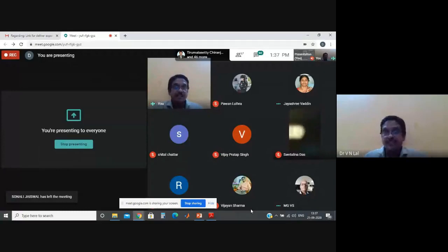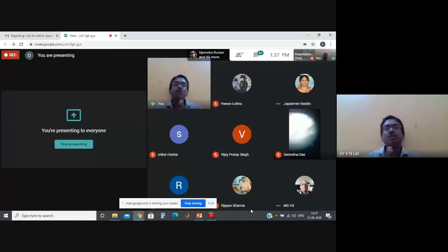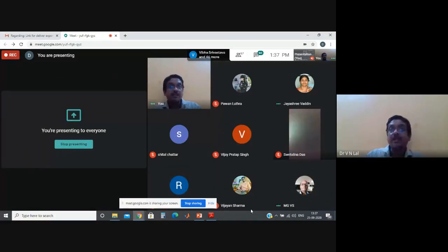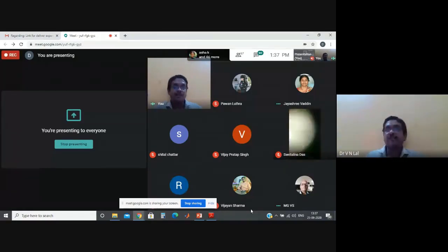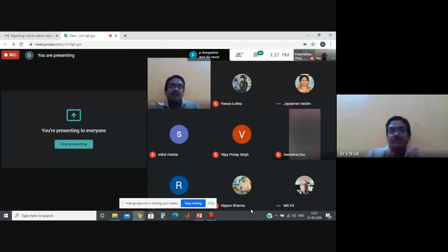If we are taking these three, I have tested it on almost 34 types of partial shaded condition, with high irradiance, 1000 irradiance, then 200 irradiance. You can take 55% as well, but if you increase the gap, obviously time will be more.